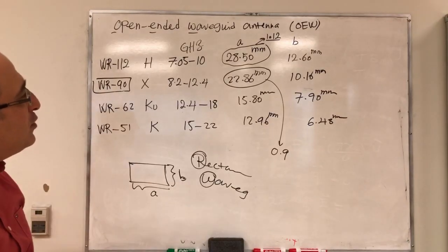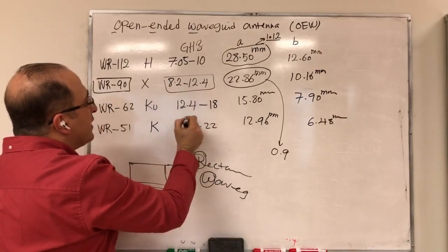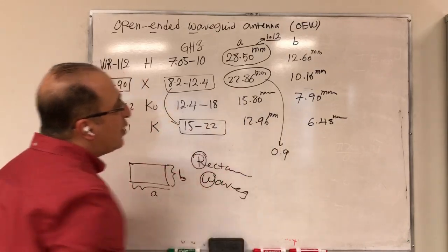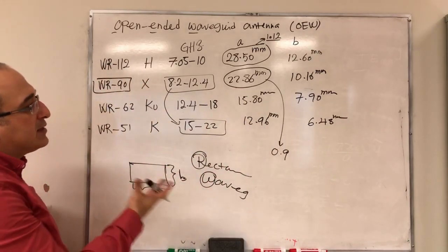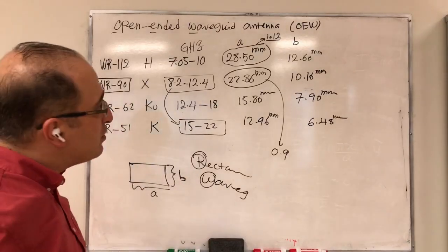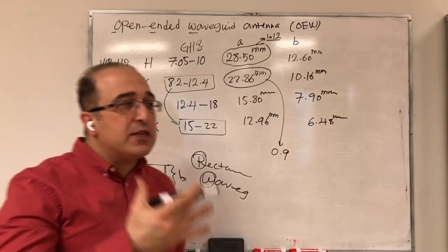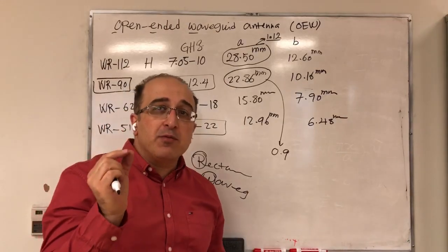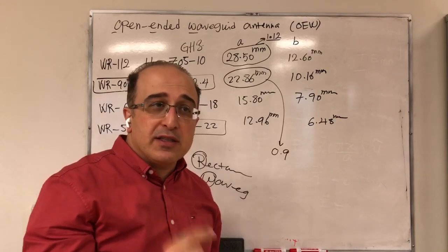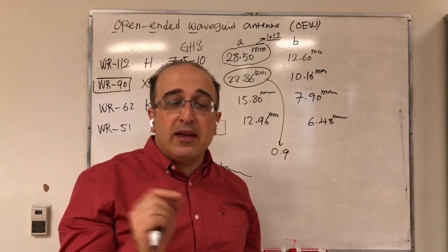The other thing that you see, as we expect, is that when the frequency goes higher, the size gets smaller here. So that's what we discussed. Or if the frequency gets smaller, it becomes bigger. So remember, when the frequency goes higher, the size becomes smaller. So you need to be very careful with fabrication accuracy, because then just a small mistake could be a big thing in wavelengths.